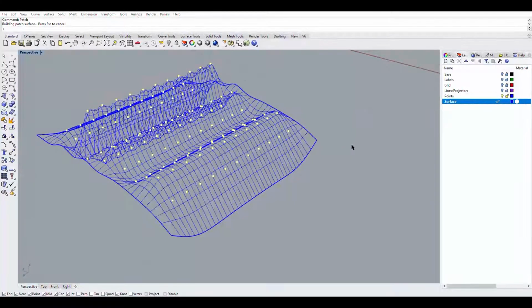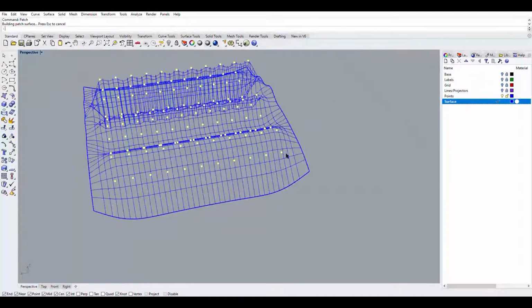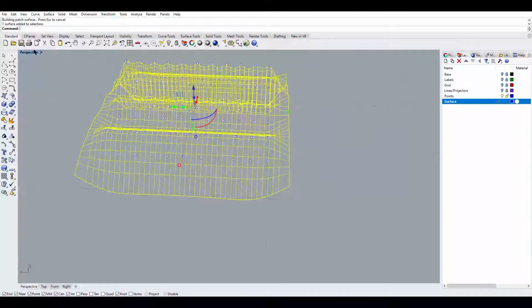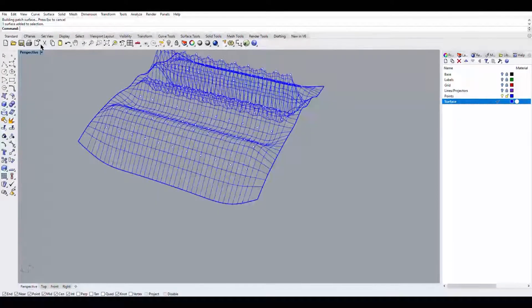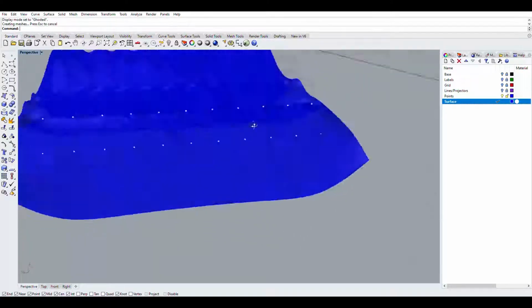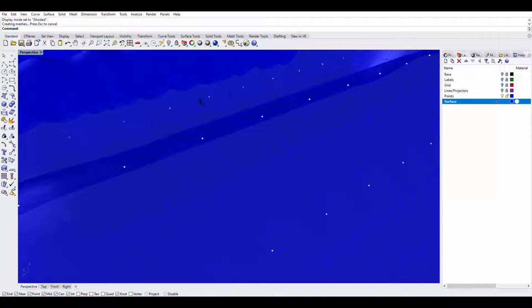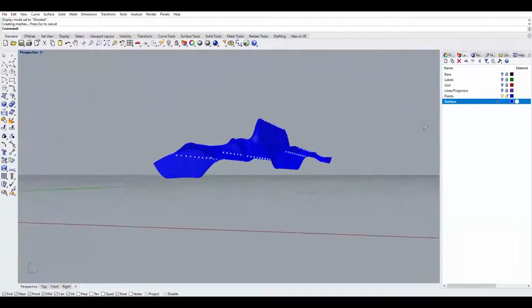We do an automatic trim that'll trim it off right at each one of these kind of endpoints. And I'm going to show you a different way to kind of generate these. So right now, it looks like it's a wireframe, and that's because if we go to our dropdown, we're in wireframe viewing. I typically like to model in shaded, ghosted, is my preferred. Ghost is going to give you a little bit of information behind the surface. So right now we can see that there is a solid surface generated.